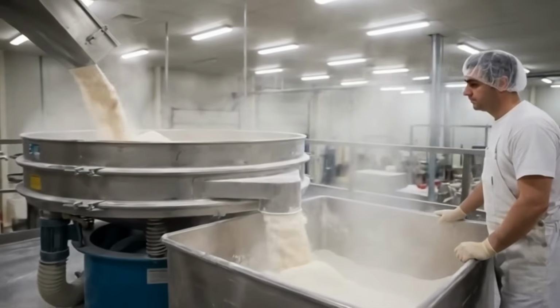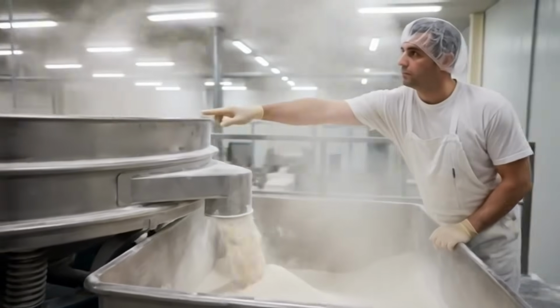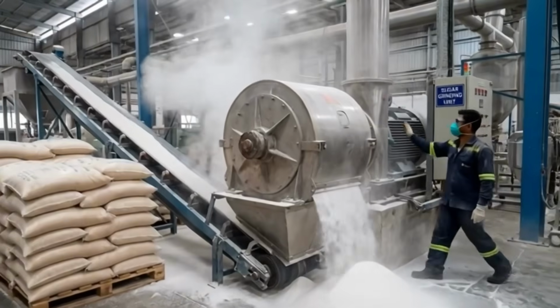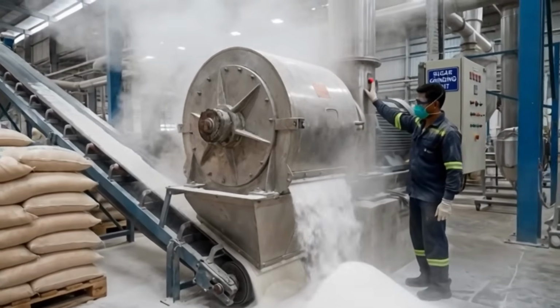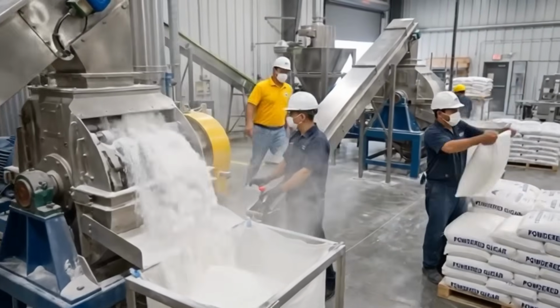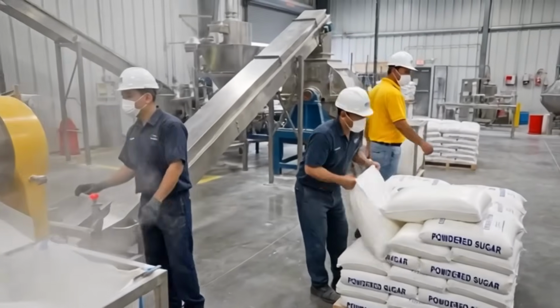Flour temperature and moisture are monitored because they affect water demand. If flour is warm, the dough softens and smears in sheeting. If flour is cold, the dough can crack and resist forming. The line, therefore, conditions flour to a narrow temperature range before mixing.